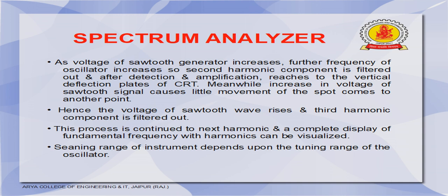So in this way, the output of the detector is given to the vertical deflection plates of the CRO, and the sawtooth signal is applied to the horizontal deflection plates, and the CRO displays the frequency spectrum of the signal on its CRT screen. This is how the spectrum analyzer works, displaying the frequency domain representation of the signal to be analyzed.